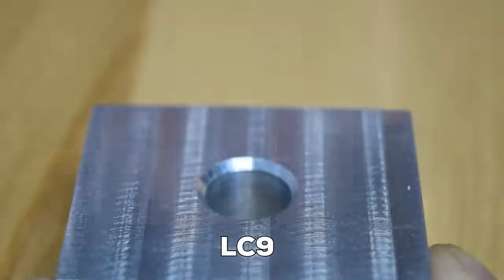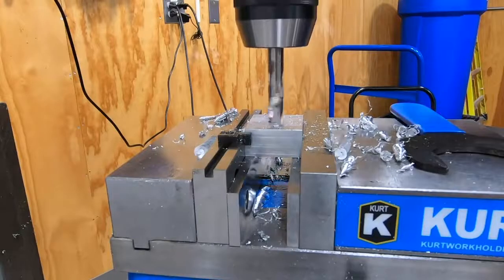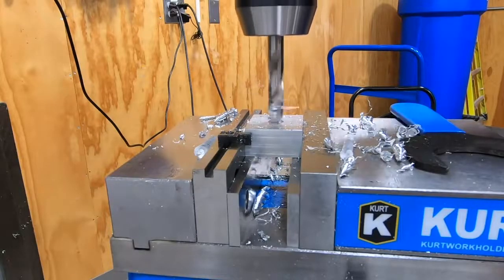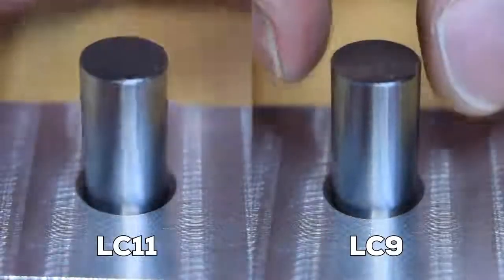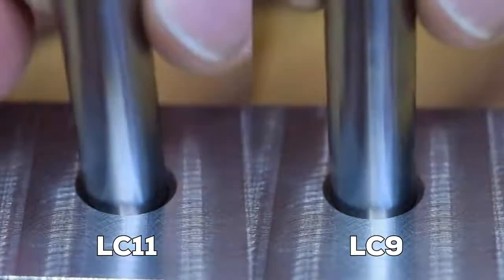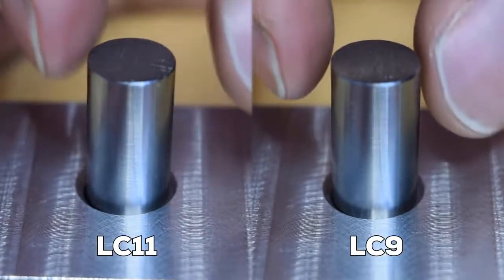It provides less clearance and has a tighter tolerance than LC11. This is probably about the tightest hole tolerance that can be drilled, but turning shouldn't be a problem for the shaft tolerance. You can see that the LC9 fit is a bit tighter than the LC11, but both can still be easily achieved with standard equipment and tooling.